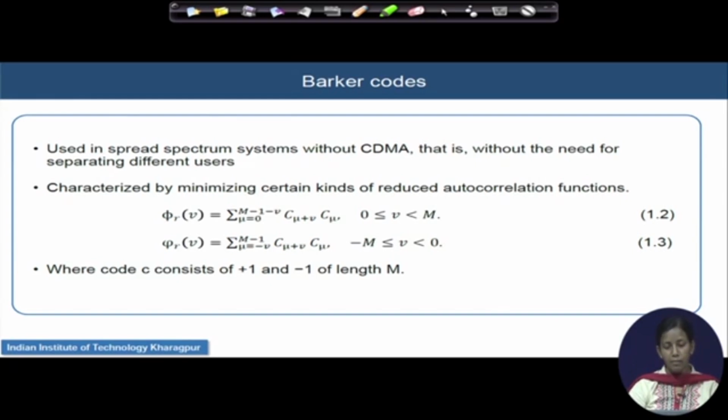They are very few in number, because of which they cannot be utilized for a mobile communication system where dense user support is required. Not only is the number of codes small, the length of the available codes is also not remarkably high. So, they cannot be utilized for code keying or as spreading sequences to avoid the jamming effect, but these codes are very useful for synchronization purposes. So, that is why we will revisit their properties.